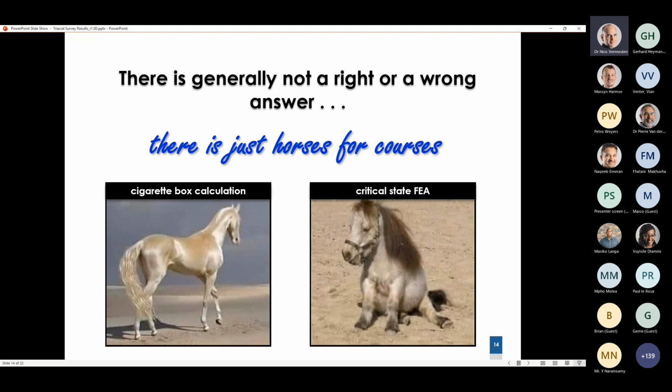Very easy to determine in the laboratory on reconstituted samples, where you don't have to worry about sampling so much. You don't have to worry how you reconstituted the sample. As long as you do it right, you will pretty much get that parameter out of the results. But in order to make a reliable estimate of the behavior of that material, you need complicated calculations. And in many cases these days, we look towards finite element analysis using complicated constitutive models which we populate with fairly simple parameters, but the mechanics and the mathematics are very complex. And so I think you have to choose the right weapon for the fight that you want to fight.